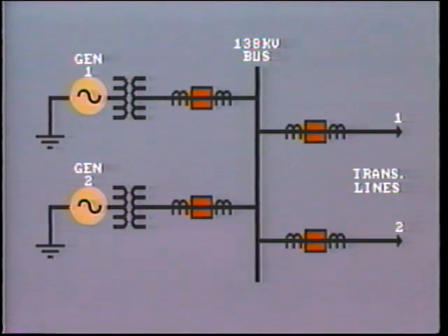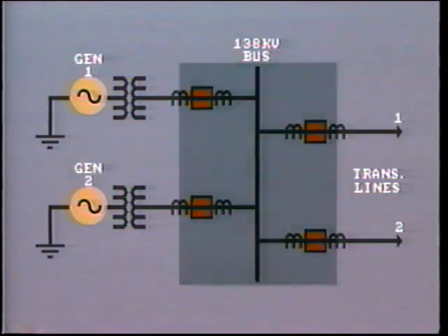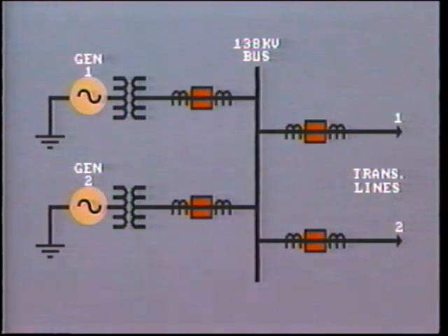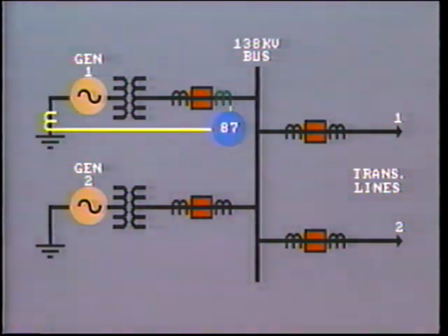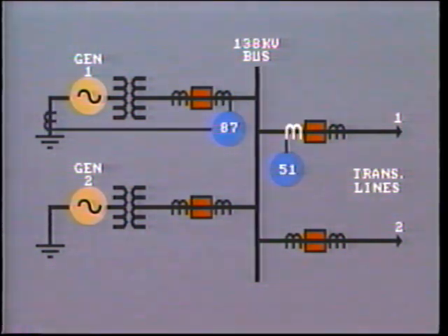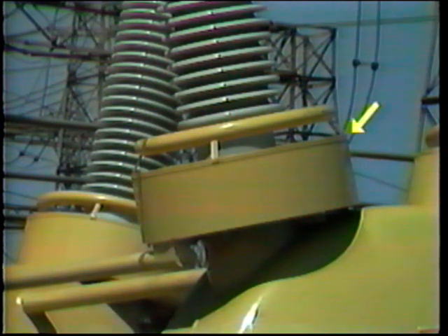The most simple is this single bus arrangement. The protected zone can be shown by this area, which extends to the outboard bus protection CTs. The inboard CT in each case is used for protection of the connected circuit. For example, in the case of an incoming generator, this CT may be connected to the generator differential. For a transmission line, this CT may be part of overcurrent or distance relay protection. The CTs are usually located in the circuit breaker bushings.